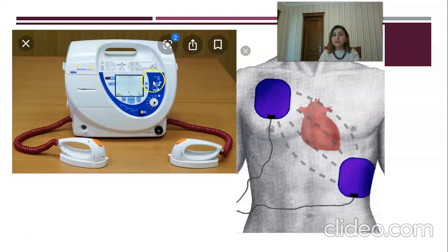But these processes can be recovered by defibrillators. It's a capacitor combined with 2 electrodes, which sends a tetanizing pulsing current. The voltage of the tool is about 6000 volts, and the energy is 200 joules. The electrodes are first put around the heart as depicted in our snapshot, and the current is sent during 5 milliseconds. This stops the working of the heart for a moment, for 5 milliseconds. After it, the functioning of the heart can be easily recovered, or synchronization will be fully recovered after several repetitions of these processes.